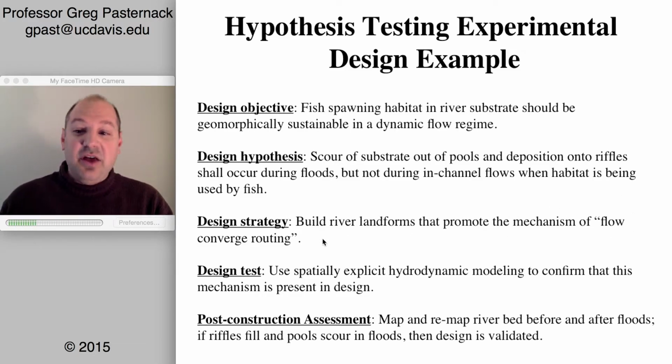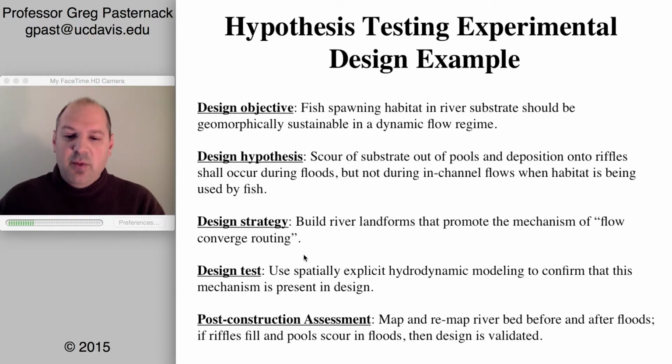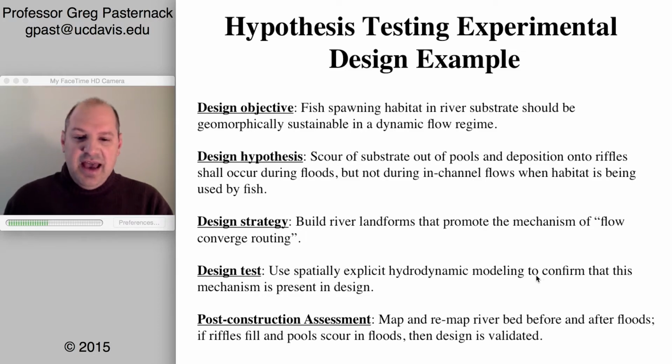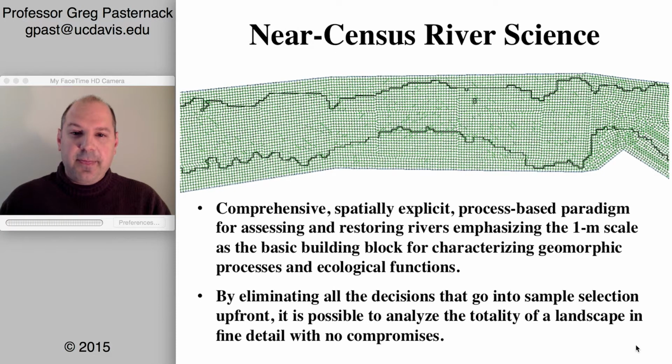And so that's another mechanism. So how are you going to test that? Well, you could make a design, you can run hydrodynamic models and see if that mechanism is there. And then you keep going until you get the design that yields that. And then even after you build it, you then see what happens during flood and find out, did in fact riffles grow and pools scour?